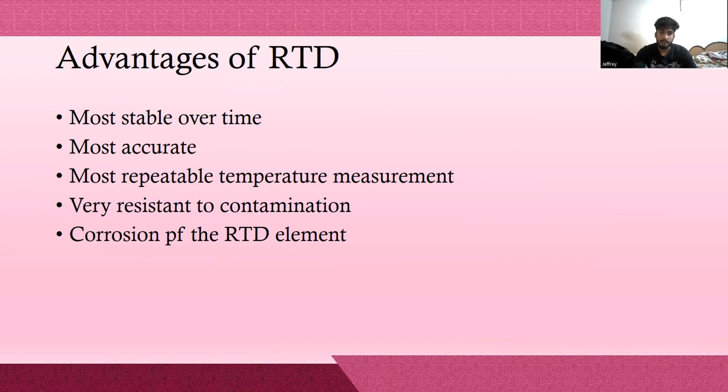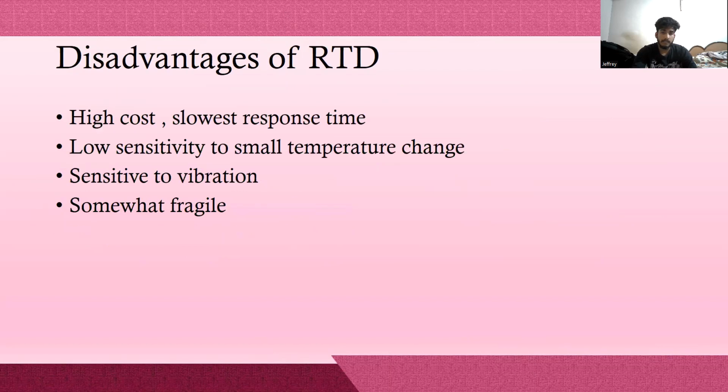Advantages of RTD. More stable over time, most accurate, most repeatable temperature measurement, very resistant to contamination, corrosion, of the RTD element. Disadvantages of RTD. High cost, slowest response time, low sensitivity to small temperature change, sensitive to vibration, somewhat fragile.